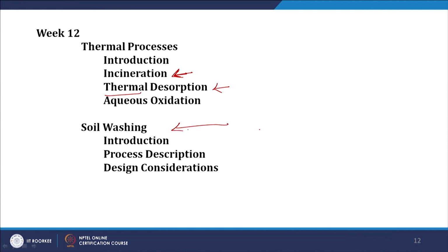And thermal desorption, right, you increase the temperature, right, again look at delta G values and such and how they change with temperature, right. You want to increase the desorption and thus thermal desorption. And then lastly, soil washing, as the name indicates, it is soil washing, as in you literally wash the soil, right, and we are going to look at that particular design. So with this particular session, you should have an overview right now about what it is we are going to discuss in greater detail.